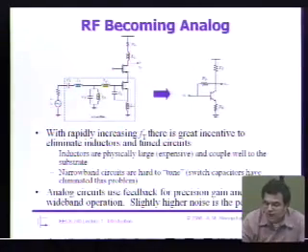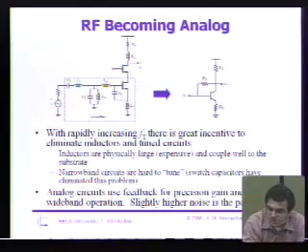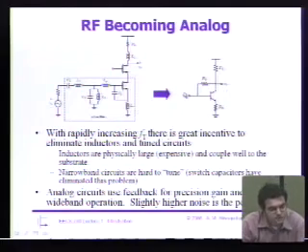If you go to an analog solution, here I'm using shunt feedback to basically synthesize a low input impedance. I just need to use resistors, and resistors are much smaller than inductors. So if you compare the layout of this to this, it might be 3, 4, 5 times smaller. What are some of the other benefits of using analog circuits as opposed to this circuit on the left?